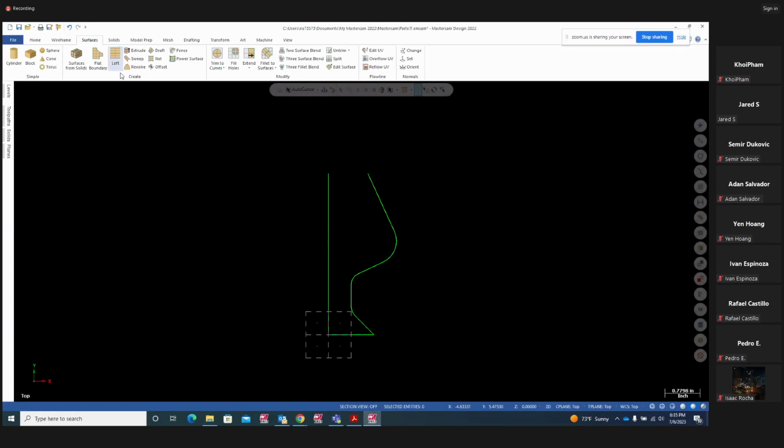So surface revolve creates a surface from a profile that is spun around the axis. It has to revolve around the axis. You have to have an axis. The length doesn't matter. We have that length 3.5 inches just to intersect, trim this to 3.5 inches. That's why. You can have even a small line of axis. So let's go to surfaces, revolve.